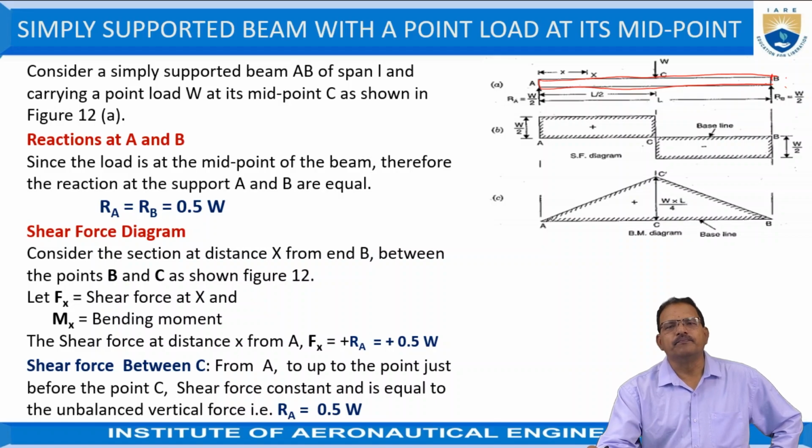when it is in equilibrium, the sum of the forces acting along the x direction should be equal to 0, and the sum of the forces acting along the vertical direction is also 0. And the third condition is that the moments created by these forces at any point should be equal to 0. According to these conditions, since there are no horizontal forces acting on it, we are limited to only two equations. The sum of the vertical forces should be equal to 0, and the second one is that the moments created by these forces at any point should be equal to 0.